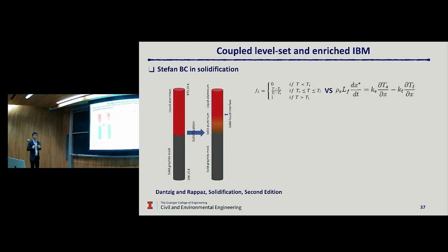Normally, including myself previously, if you use the diffusive interface approach, you have to introduce the liquid fraction to handle the boundary condition. And I remember when I was at Northwestern University, when I worked with the diffusive interface approach, I read a lot of papers from Professor Voorhees regarding the models for those liquid fractions. But this is a diffusive interface approach. If you have the enriched immersed boundary method, you can actually enforce them in a better way by using this enriched DOF concept.